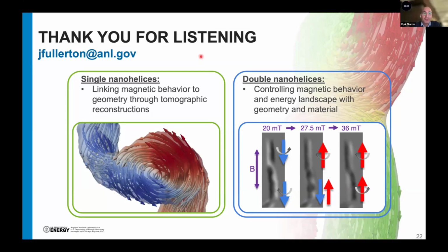Okay. And before, you used this planar structure, and then you focused the electron beam to cut through the sample, right? No, it's more like an additive process. You inject this precursor gas in, which will absorb to your substrate, and then the electron beam will break it open and leave behind just the cobalt in this case, and create little deposits. Then by scanning the electron beam round in a helical-like fashion, you can create these spirals and structures. So it's like a growth. It's like a 3D printing type process.